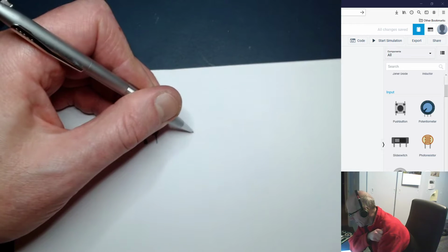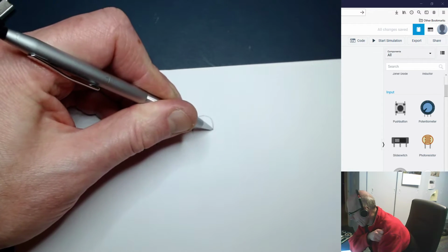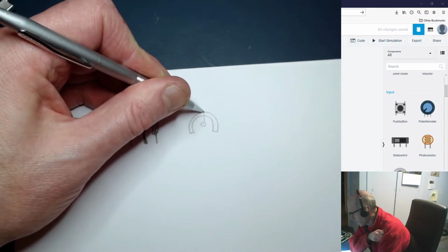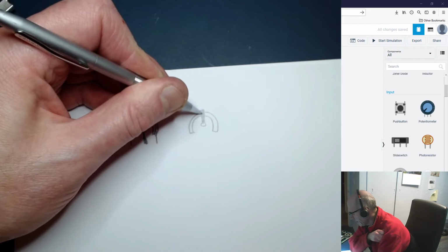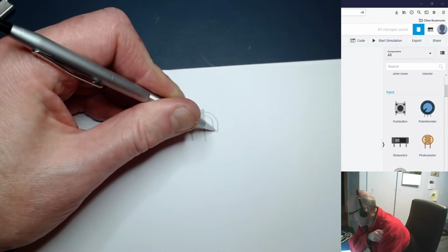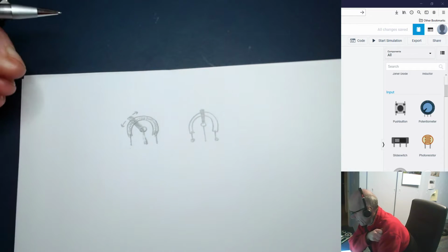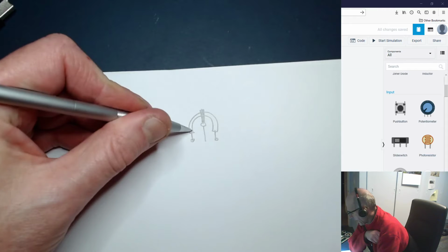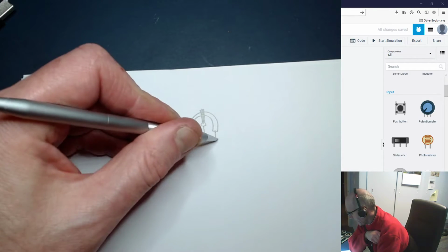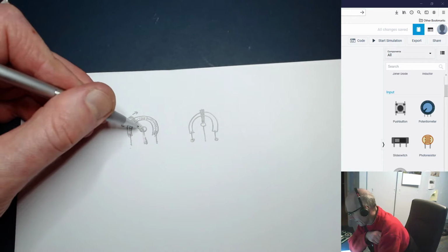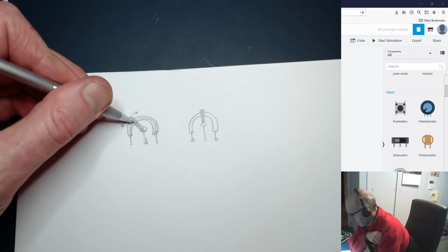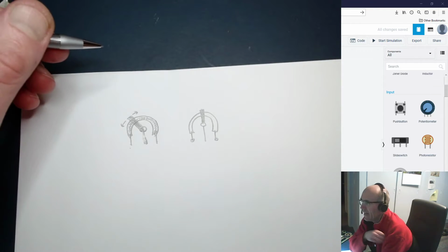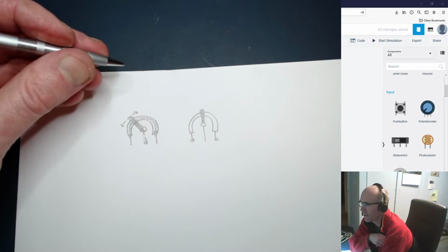So electrically right now, in this position, this pin is closer to this pin than it is to that pin. When it's perfectly up and down, it's halfway in between. Now, that's useful for a lot of things. If you want 5K of resistance between this side and 5K between that side, you're great. If you want about 3K and 7K over here, that works out as well. And you'll see when we talk about voltage dividers, that makes a lot of sense.